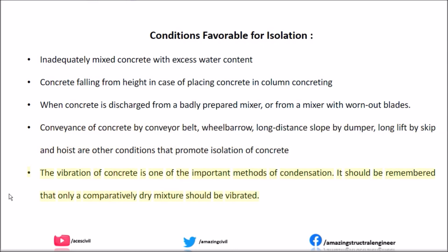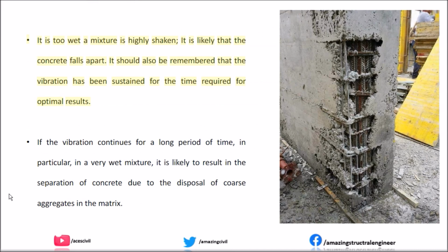The vibration of concrete is one of the important methods of compaction. It should be remembered that only a comparatively dry mixture should be vibrated. If a mixture that is too wet is highly vibrated, it is likely that the concrete falls apart.